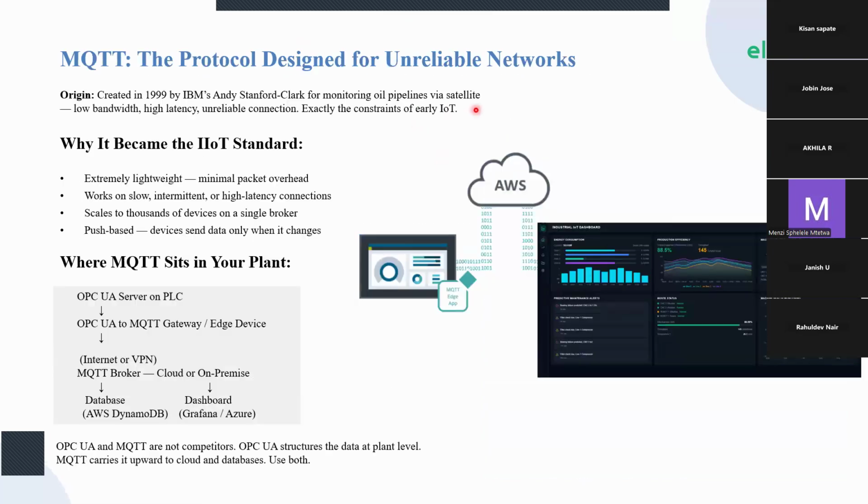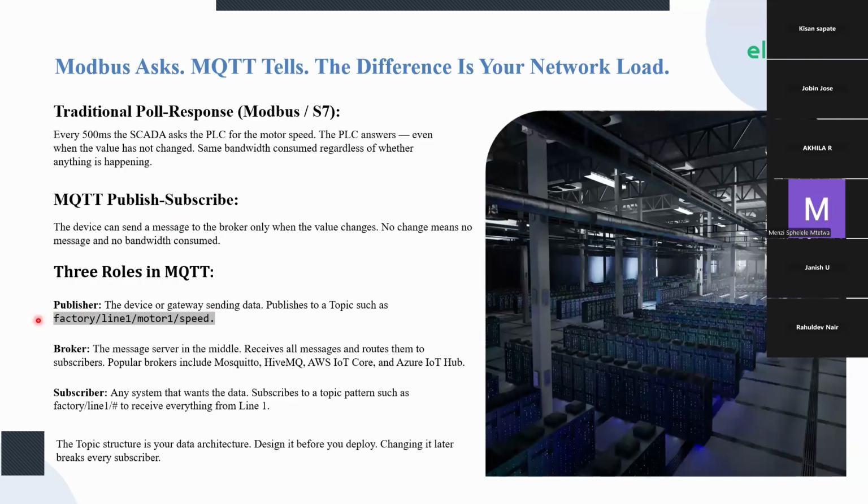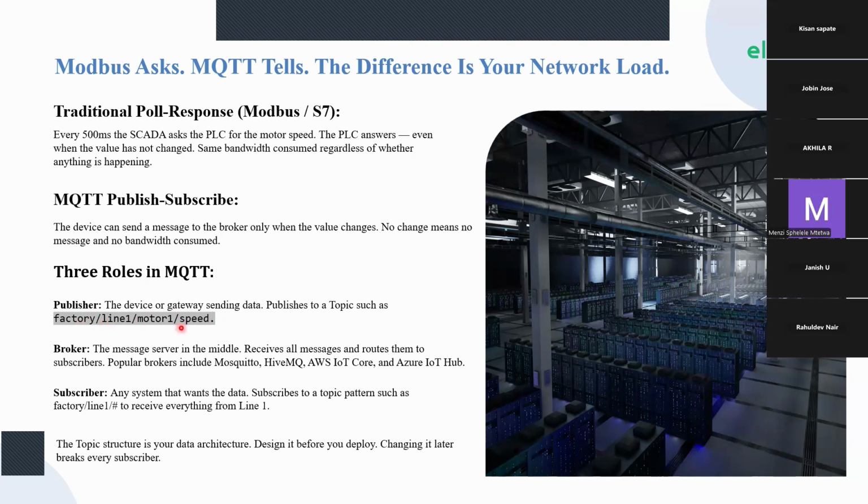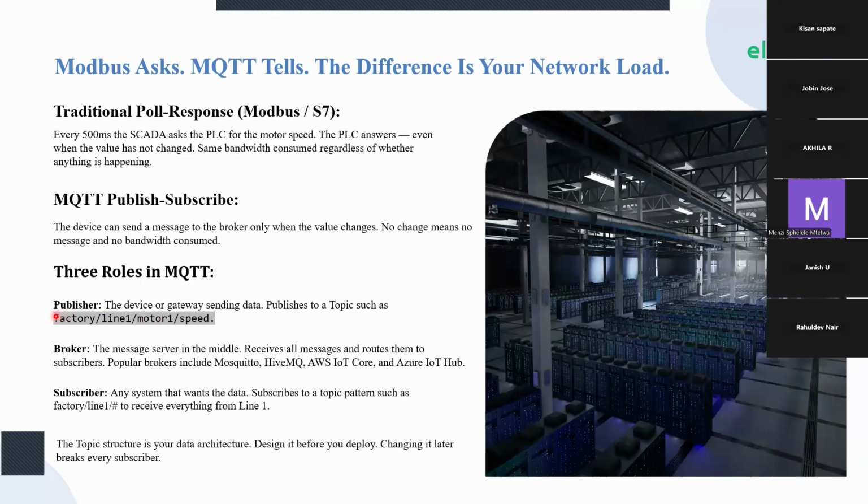This is actually a method of data structure in MQTT. You can see that the OPC way and the MQTT way are a lot similar, because we can categorize the data with this method, like we discussed in the unified namespace. With all the data coming from the factory, it's very difficult to determine from which area a single data point is coming. So with OPC UA and Modbus and MQTT standardization, we can have a unified namespace across all the data communicating between the factory and the sensor level itself. You can categorize the data very easily.